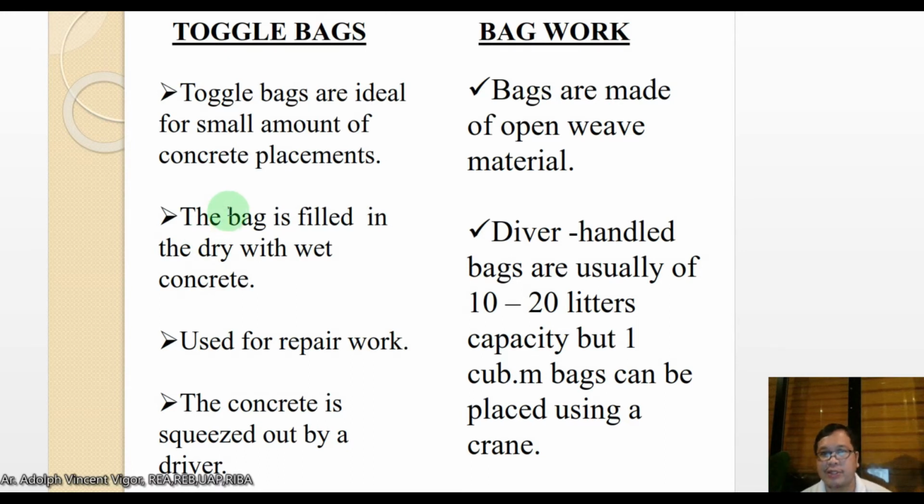So let's compare toggle bags and bag works. Toggle bags are ideal for small amounts of concrete placements. The bag is filled in the dry with wet concrete. It is used for repair work, and then the concrete is squeezed out by a diver.